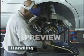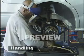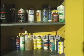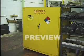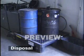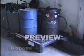The handling stage is workstation operations, when you're using flammable liquids as you work. There are many workstation cans and tanks from which to choose. Liquids should be stored in safety cabinets near the workstation. Disposing of waste flammable liquids requires as much caution in handling as do any of the other stages.